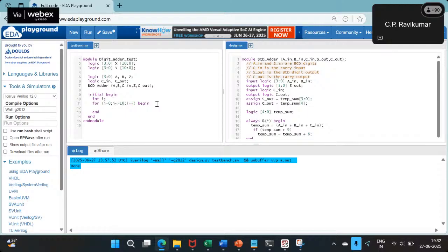So initialize x and y. So x of i equals, let us say, $urandom_range 0 to 9. So it gets some arbitrary BCD digit. These are my inputs. I have some 11 BCD digits.